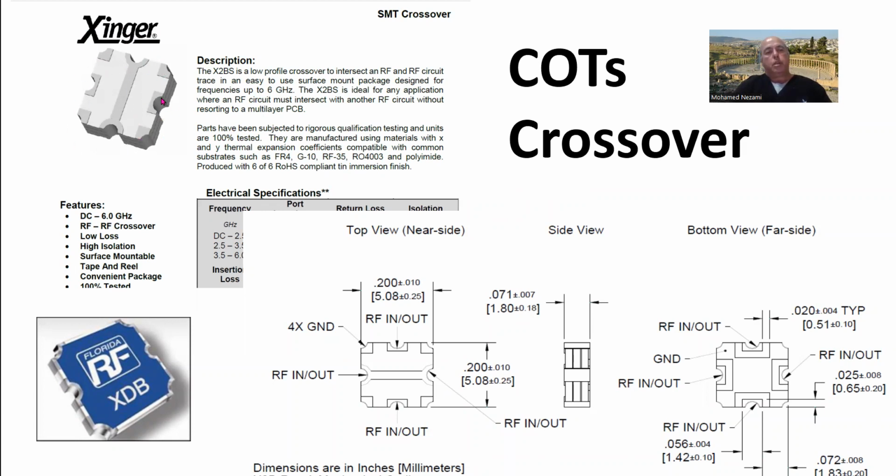So as you can see here, one of the signals goes in here, and in a stripline, it goes to the other side, while the other one is a microstrip line and it goes on top. So that's what you see in here. RF in, out, in, out on this side. Same way from Florida RF Labs, and I think this one is now not Florida RF Labs anymore, but Smiths Interconnect probably. These things you can see often, and they're usually good to somewhere around 6 gigahertz.